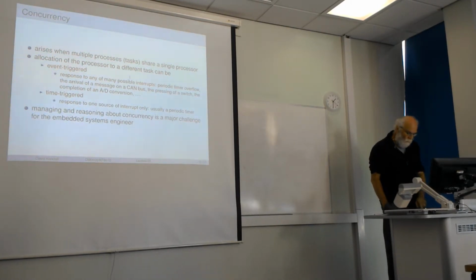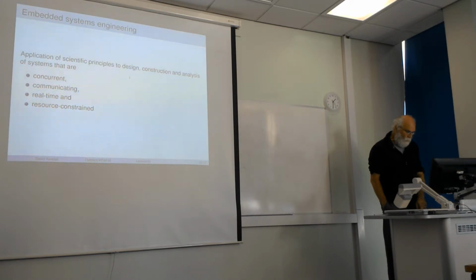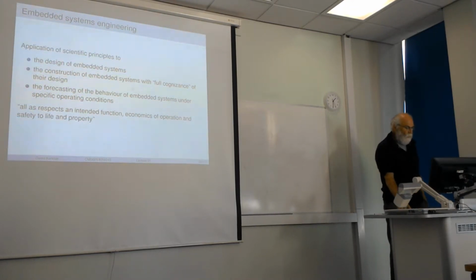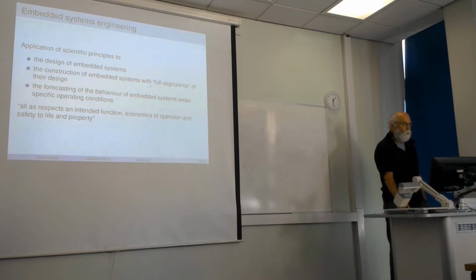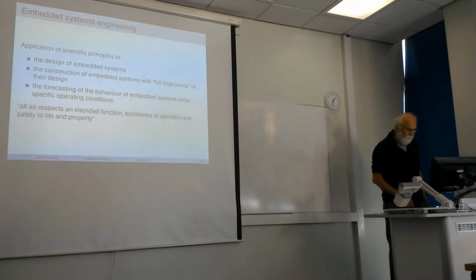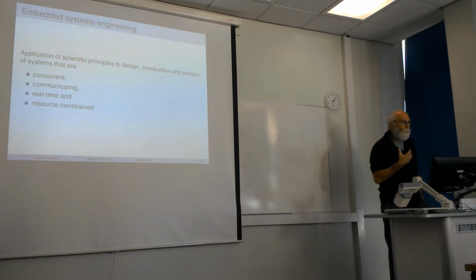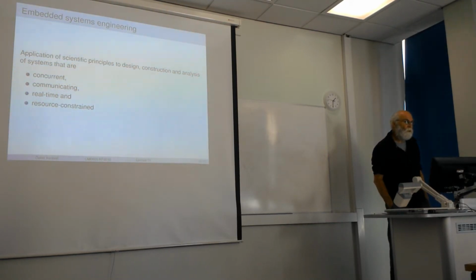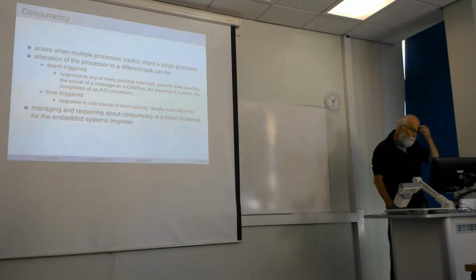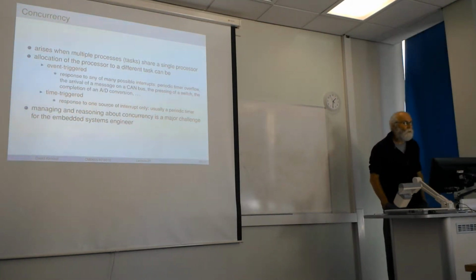So if you're thinking about this issue of the construction of a system with full cognizance of their design and the ability to forecast behavior, then you might be pushed towards the time-triggered approach. But if you're trying to make your system responsive and perhaps make better use of resources, then maybe you push towards the event-triggered approach. So we've got some design choices to make.